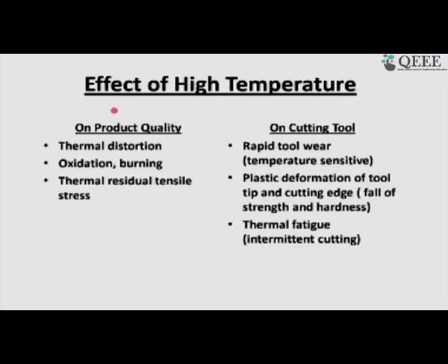Whatever I have said about rapid tool wear may happen during continuous contact, say high speed turning, where the chip is continuously flowing. But thermal fatigue is like interrupted cutting, where the job may not be a regular one, or say the best example would be a milling cutter.